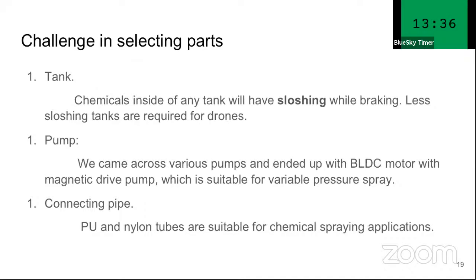So we will actually now indicate these waypoints, and then we will go back and get this drone to do this rastering. So every time it goes from one end to the other end and stops, and then it has to displace itself to the next row, there will be a sloshing of the liquid within the tank, and the sloshing actually ends up destabilizing the drone, right? So we need to try to arrest this sloshing. So some tanks that are well crafted and well designed will have baffles within in order to try to accommodate this sloshing and try to alleviate that problem.